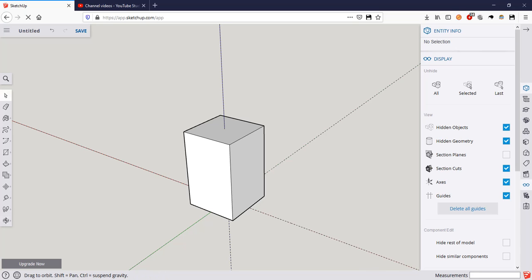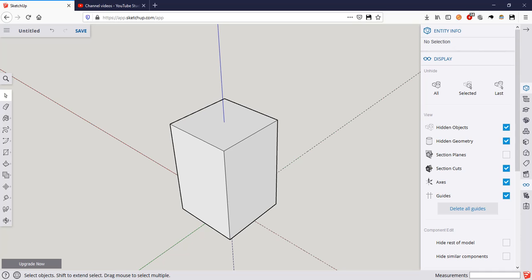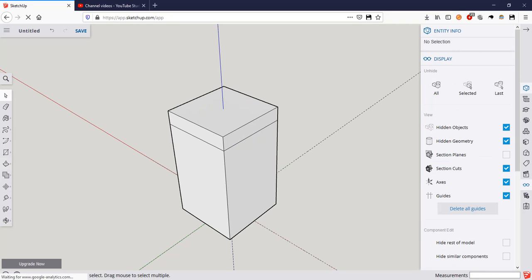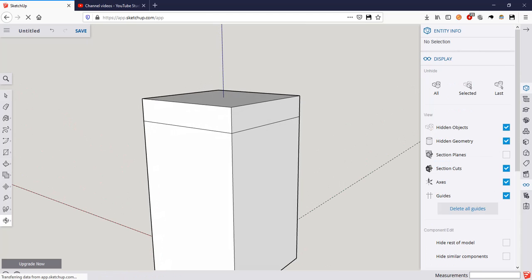Okay, so I wanted to show you something cool. If we select this face and hit P for push-pull, notice there's something down there that says, if you hit Control, it'll be a new selection. So if I hold Control, notice how the plus sign shows up, click it and move up, and then I'm going to type in 10. There we go. Sorry, it wasn't moving up for some reason. That'll create a whole new face.